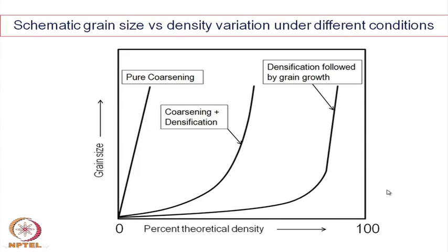In all ceramic systems, less than 90% density is never used, or is not a very useful product. If it is less than 90% density, it is actually porous ceramics. There are some uses of porous ceramics as membranes. There, pore size is the criterion; it is not that densification is unimportant, and mechanical strength is also important, but one has to balance how many pores are needed for the material to be used as a membrane, as a sieve, as a microfine porous material.